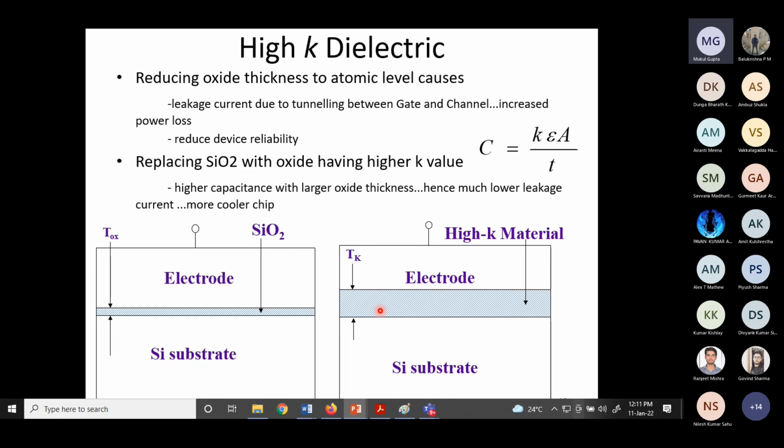So you see, SiO2 is a very important material, and over the years universities, research labs and industry have pioneered this technology. Now the SiO2 Si interface is very good, because that interface has to be defect free, otherwise channel electrons or channel holes will suffer, their movement will be affected when they move between source and drain, right?